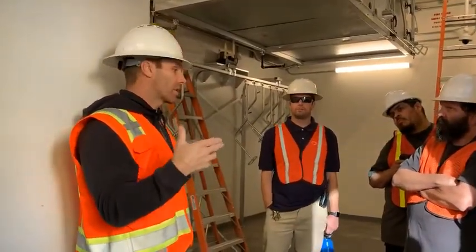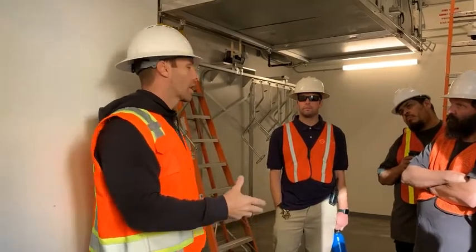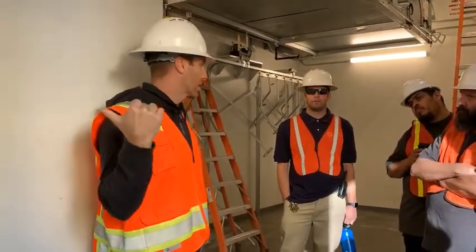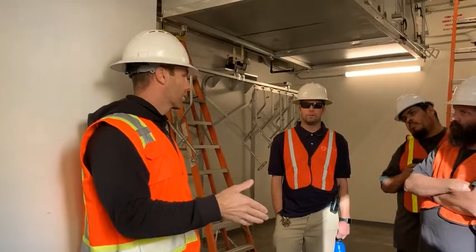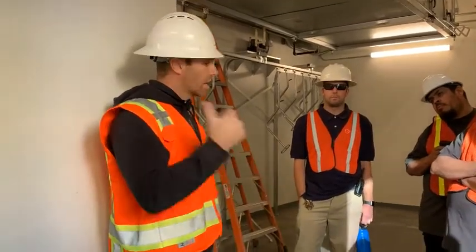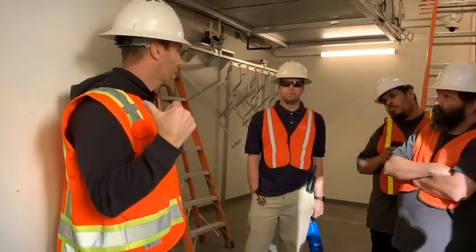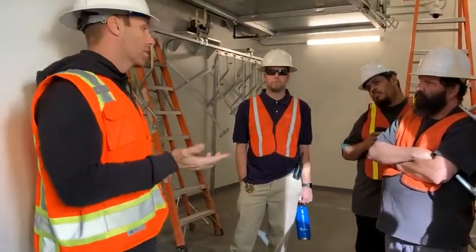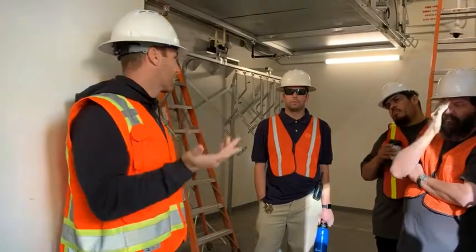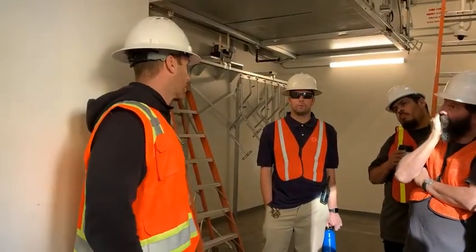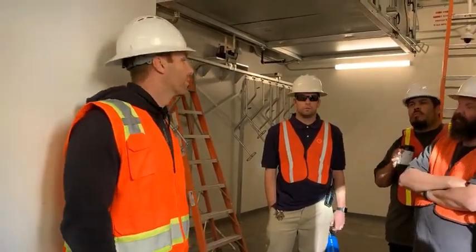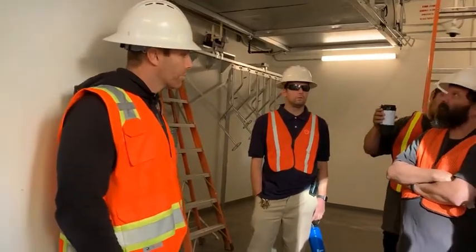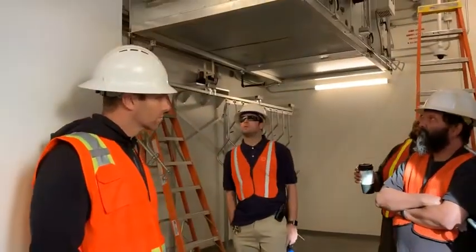Right. If for any reason the campus wants everything on their network, they could pull a Cat 5 from each Eclipse and drop it to their local switch, whatever that may be. Each one you can change the IP address on and be able to see it through our software. If you want to do BACnet, you can do the same thing, it would just be changing the IP address.